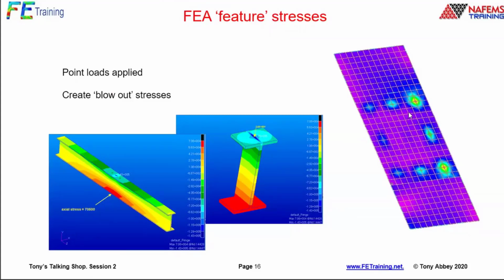It kind of tries to recognize the singularity and then says, I'm not actually going to show the stresses around the elements around there. I really don't like that. If it's bad news, I want to see the bad news and then fix it up. Or just say, I've set the contour legend or contour levels myself to deal with that. And again, a methodology explained.